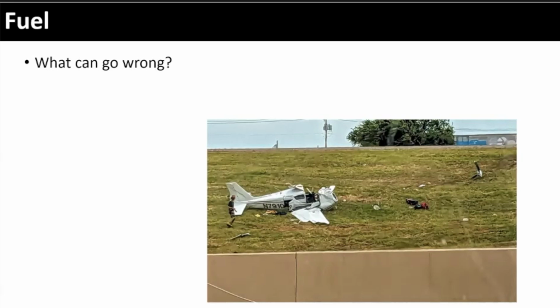I actually have a student who has his own plane down in one of the hangars, and one day he was testing the fuel, and it was blue, but it was really differentiated from the white. It wasn't that normal kind of, I don't want to call it bright blue. We chose not to fly that day until he had the fuel tested, just to make sure. If you hold that up to the white wing, it's a very distinct blue.